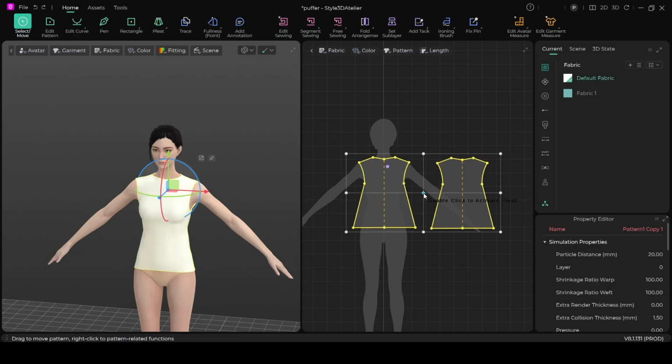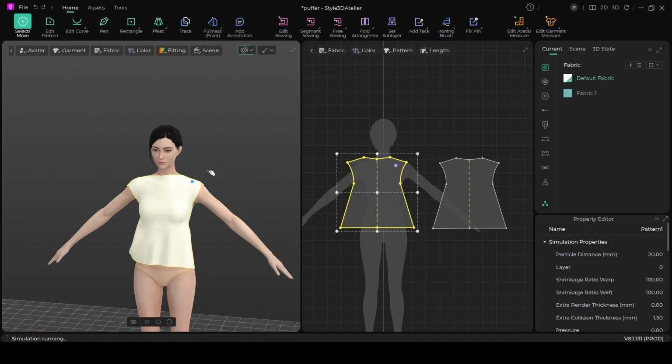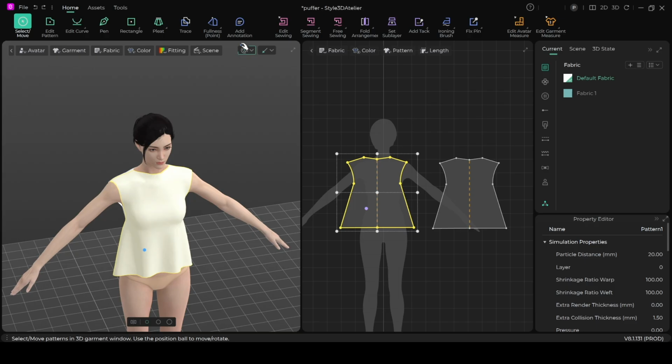And then you double click on the center dot, and then at the side here, because we want the width increased, we just drag. We simulate, and here we are. So this is a bit bigger, because as I've said, I'm only going to do it to the front, just so you have an idea and that you can practice doing it this way.